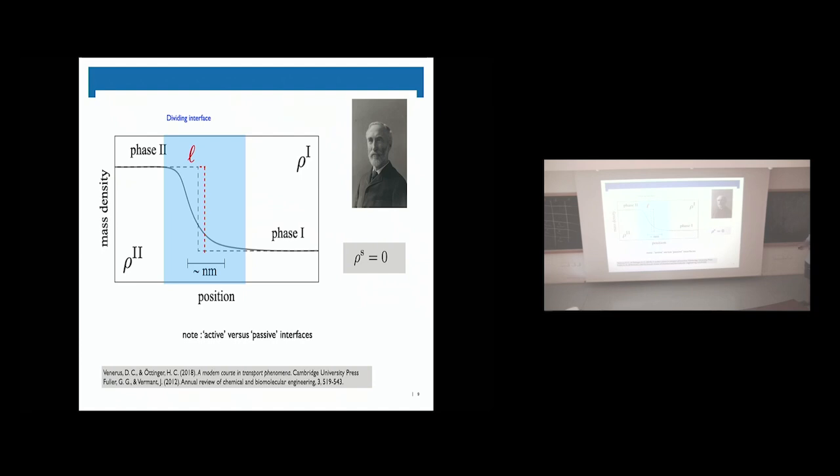But for example, the temperature discontinuity does not need to be in the same place. The concentration of species, if I have 5, 6 components, they all live in that interface, but not at the same place. And this can make things complicated. If you have transient systems where you have diffusion to and from the interface, or if you have non-isothermal systems, you have to be extremely careful how you do that. Today, I will only talk about so-called passive interfaces where I don't have these concentration fields and temperature fields living there, because it makes my life too complicated. But when they do, you have to solve additional partial differential equations that describe the evolution of that relative to the interface that you follow, okay?